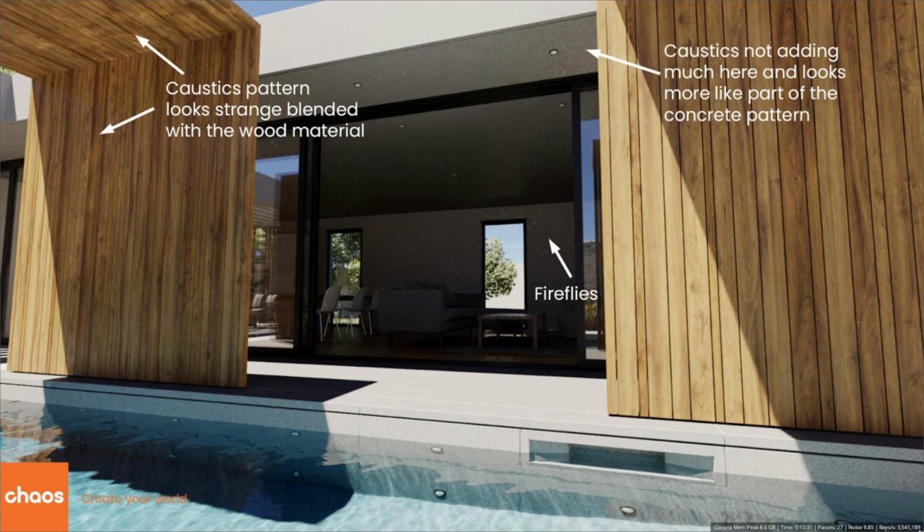They're not that visible, right? And they kind of look like they're part of the concrete pattern. And if you take a look at that back wall in that interior there, you're going to see that we have some fireflies happening. Well, with the Include, Exclude functionality, what we can do is set only certain objects to be receiving caustics or displaying caustics. Or if we turn that around, we can exclude objects from receiving caustics.